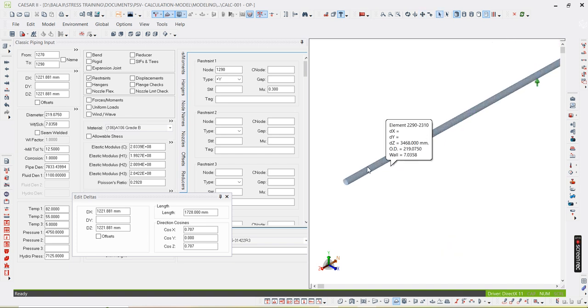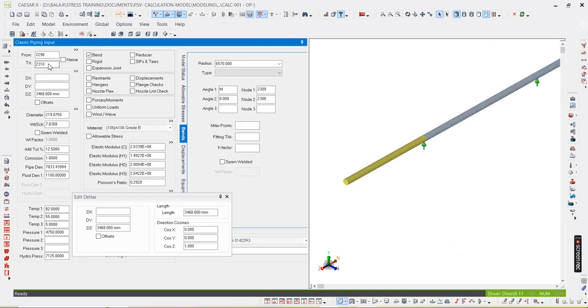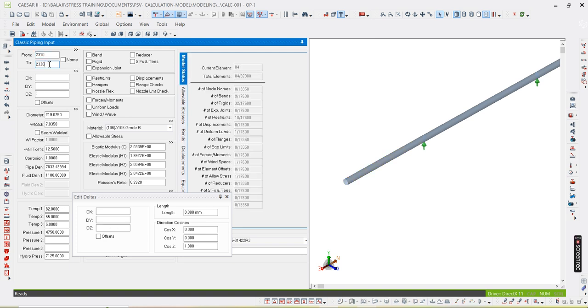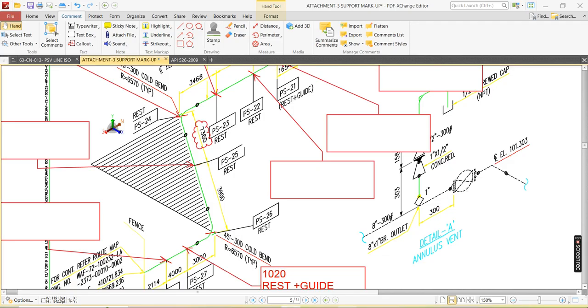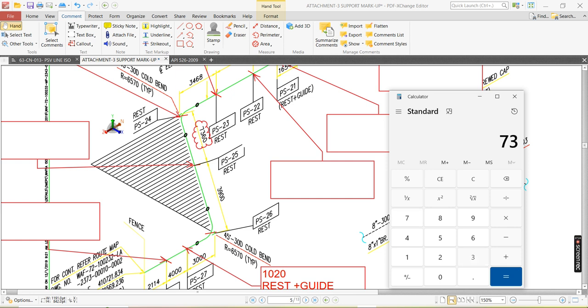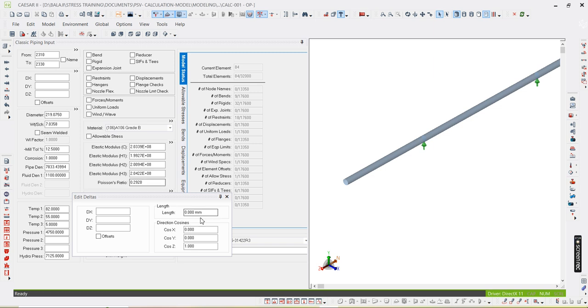Okay. So here we see what we are going to do. Since we don't know the value of this, we will enter the overall dimension. 7360 plus 3900, 11260. We enter this diagonal value here, 11260. Because your previous node is in z direction, it automatically considers that direction only.